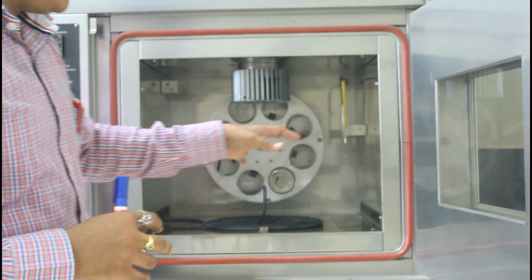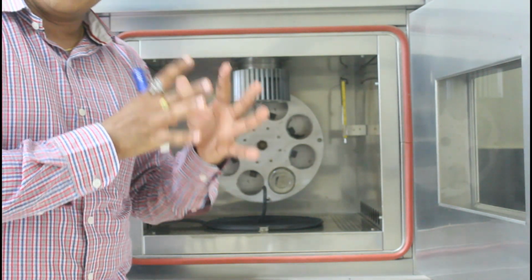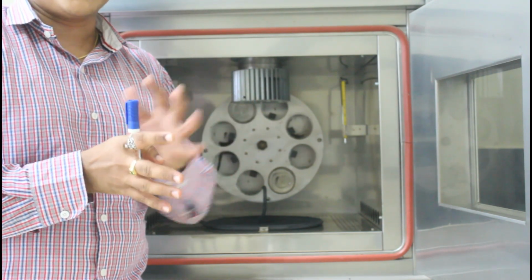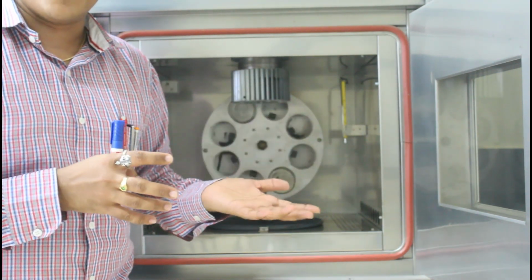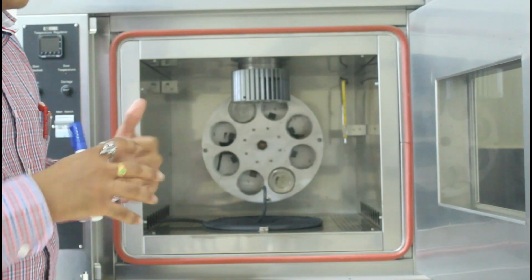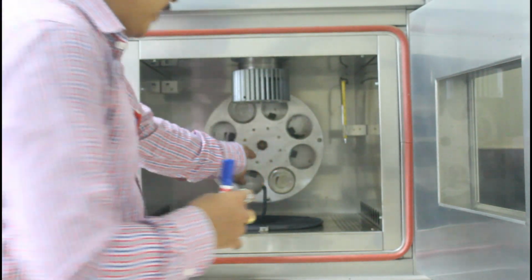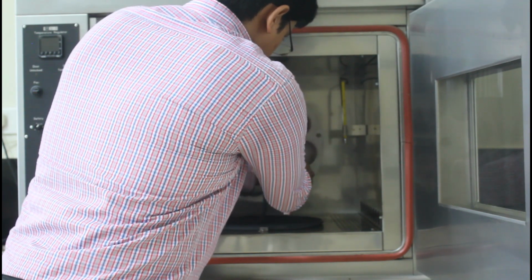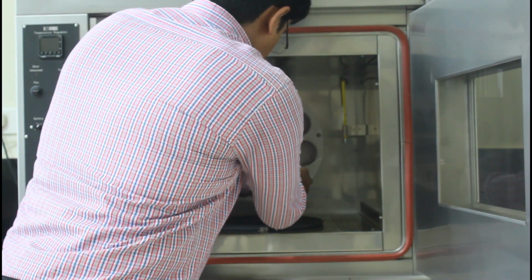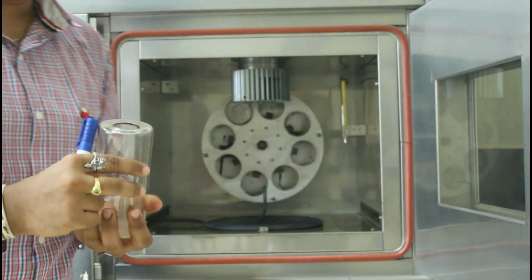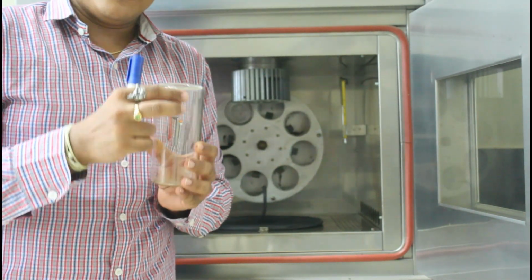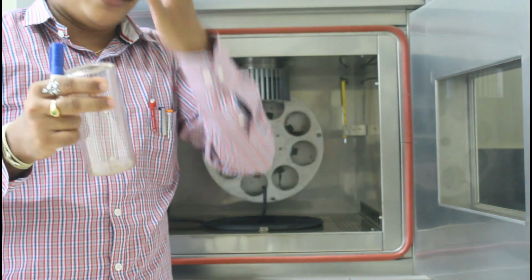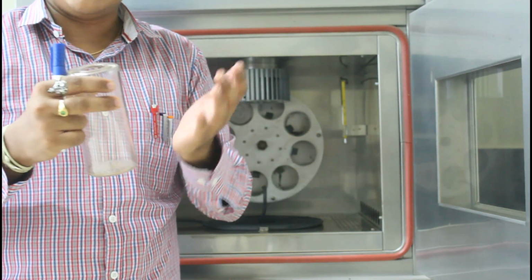Now let's say, as I told you, we can do two kinds of things. One is you can determine the mass loss. The other thing, you can determine the rheological properties or other properties before and after aging. Now let's say if you want to determine the mass loss, we will take these particular RTFO bottles. We take the RTFO bottles, then we will allow them to cool. Right? Then after cooling, we will see what the mass is. We will compare the initial mass and the final mass and see the mass loss.